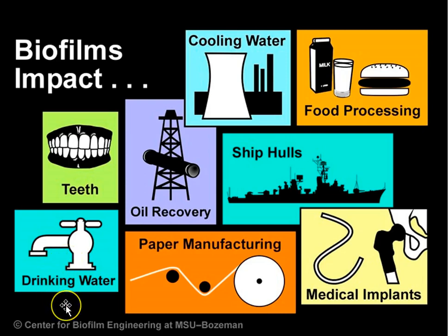And it's one of the cases where you don't want to dose your chlorine so high that it stinks when it gets to your use. So in general, there is a trade-off. You accept that there is a little bit of microbial activity in your pipes, but not so much that it's ever dangerous or visible.